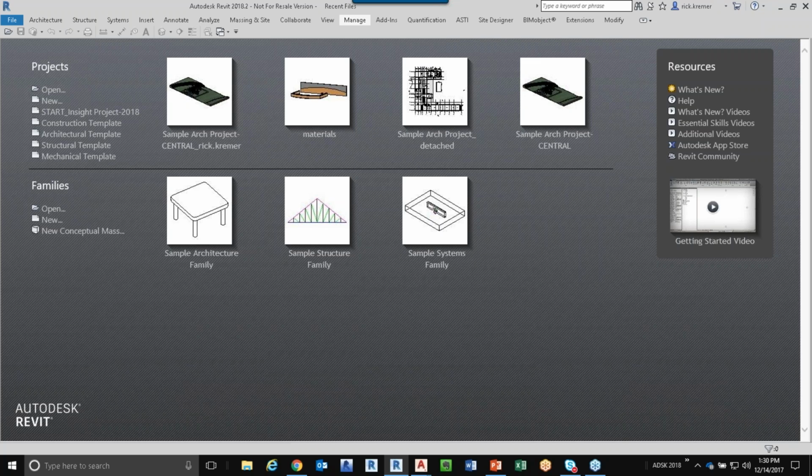Let's say I'm the architect, I have MEP and structure, and those are separate linked files. As the architect, I want to basically unload those files and then separately send those out as detached files. As the architect, I'm hopefully going to be receiving detached files from my engineers. The only central file will be mine. So I only have to detach my model and then send the rest of them over together.